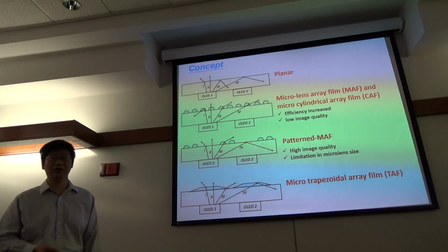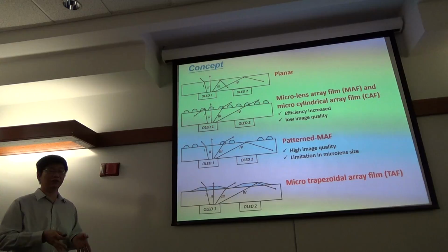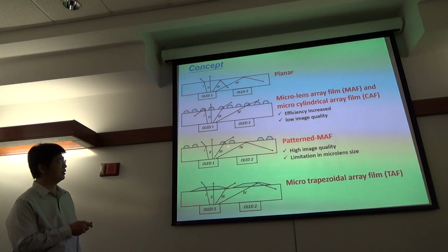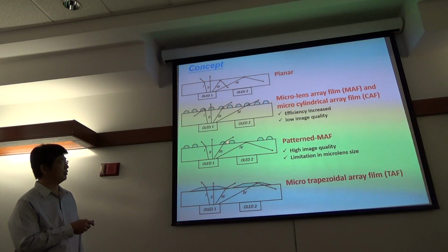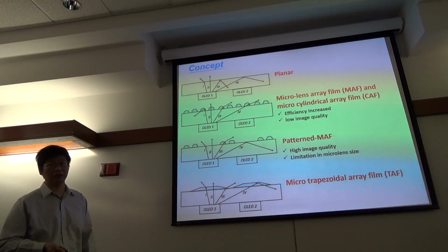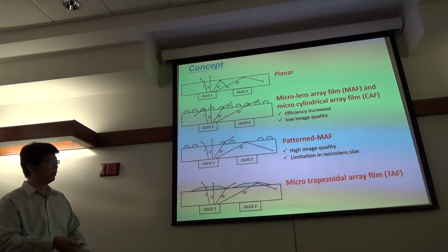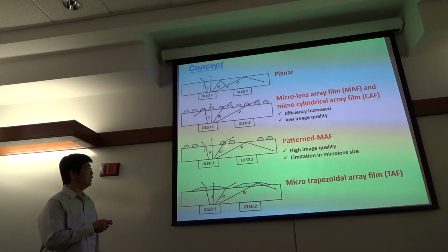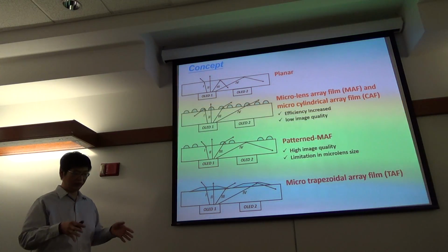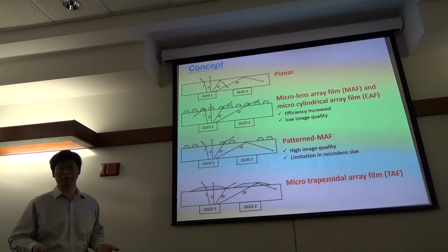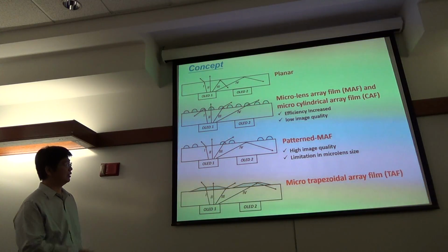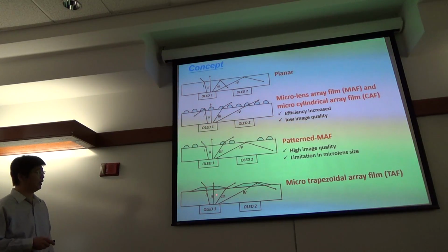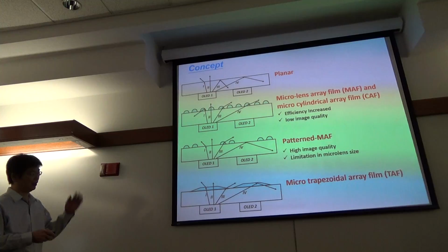And the other thing is, during mass production, we have to consider the gap. There is a minimum requirement of the gap. For example, 2 micrometers is your limitation. So you cannot have 1.5 micron, 1.1 micron. It's not acceptable. So when you have higher and higher density, I mean higher PPI, then you will have a smaller aperture ratio. So we said, okay, why not, actually we just need some non-planar structure.